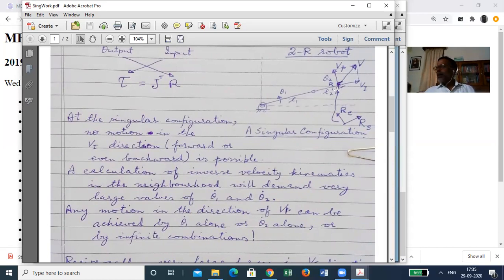And the two are related. Because if motion is not possible by input torques as well as output forces, which is the same thing because it is locked, if motion is not possible, then why is motion not possible? Who is stopping it? Okay. So it is the joint reaction which is stopping it. Okay. And joint reactions up to the capacity of the joint will take forces. So whatever effort is there to push it in that direction, it will be stopped.